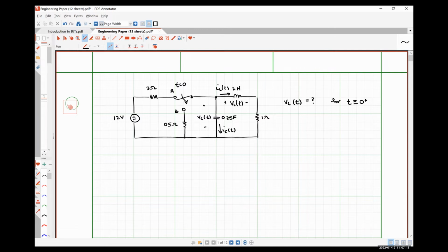Okay, so there's a couple of things I didn't care for in your response. We only consider whether this is a series, parallel, or general during the transient condition. So what it looks like prior to the transient condition is completely and utterly inconsequential. During the transient condition, where the switch is closed at B, I think you said that the capacitor and the inductor are in series. I disagree with that sentiment. I also disagree that the 1 ohm resistor and the 1/2 ohm resistor are in parallel.